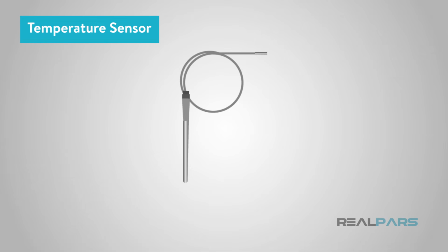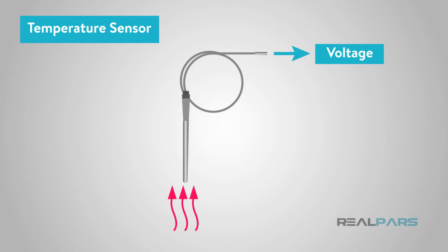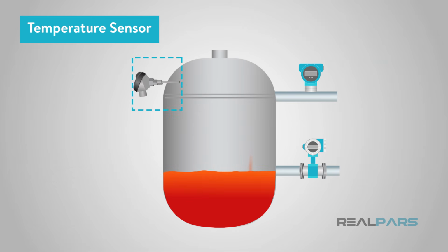Generally, a sensor or transducer is a physical device which is capable of transforming one type of process variable to another signal type. To elaborate on this generalized sentence, let me give you an example. Temperature, pressure, flow, etc. are some process variables, and actually, they are physical characteristics of our real world.